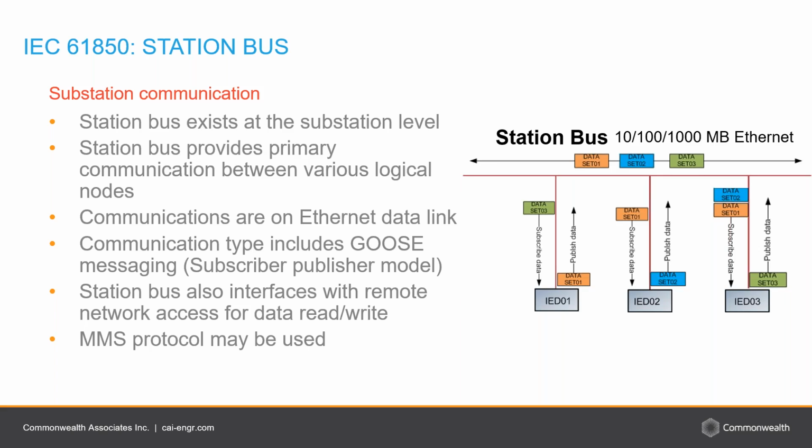The station bus can also interface with the network gateway where remote network access is possible. The MMS objects and services protocol can be used to access the data on the logical nodes of the IEDs of the substation for data read-write purposes.